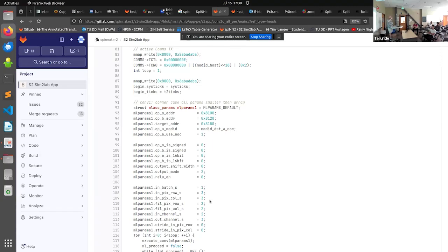and I think the output channels need to be a multiple of 4. And for example, here the stride is always a power of 2. So possible strides are 0, 1, 2, 4. A stride of 3 is not configurable in the machine learning accelerator, but that's a rather rare use case. I mean, typically you have strides of 1 and 2. So that's the things you might need to configure here.